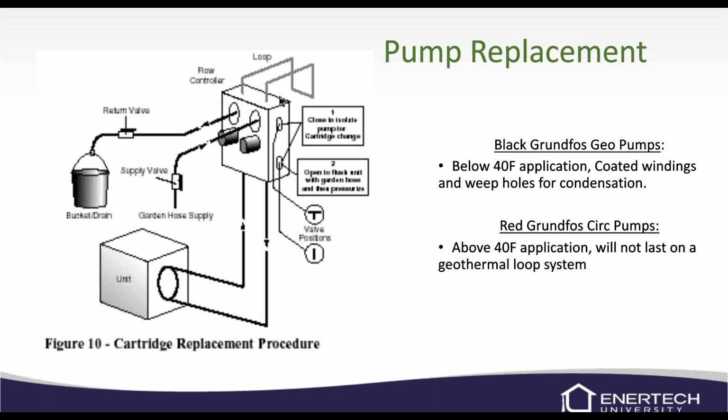So if you ever notice that it's leaking out the back of the cabinet on a brand new install, definitely look at your connections coming into the top of the flow center and make sure that it's not leaking out of those fittings. It's kind of hard to see when you look down in there, and it doesn't look like it's leaking from that fitting. So I would say that if it's a brand new flow center, it's probably not a flow center leak. It's probably one of the fittings or something like that. But we can change pumps without taking down the whole system.